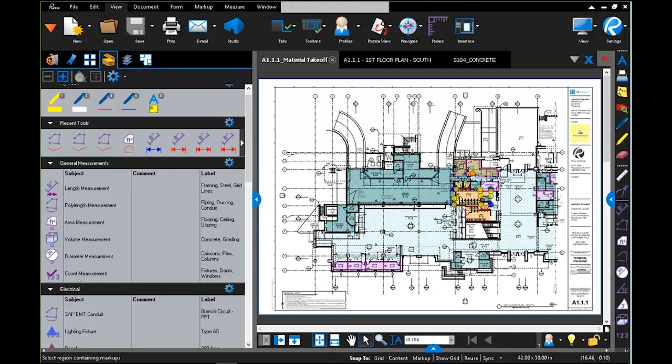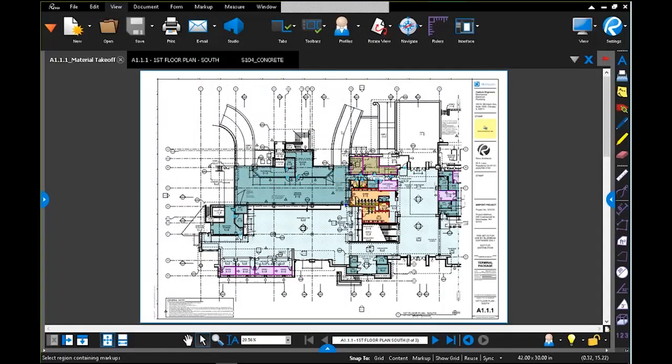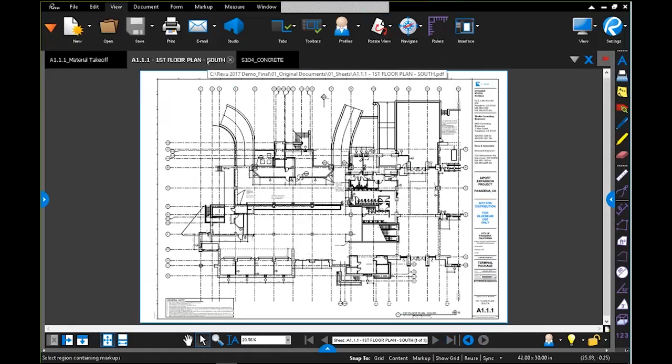All right, so in front of you, I have a document, a drawing sheet that has tons of markups in front of you. So our goal today is to get you familiarized with some of the fundamentals with our measurement suite so you can really start to achieve what you see in front of you. But the first golden rule to an estimation and takeoff workflow is to always calibrate your sheet. So always calibrate. It's the first step to do.